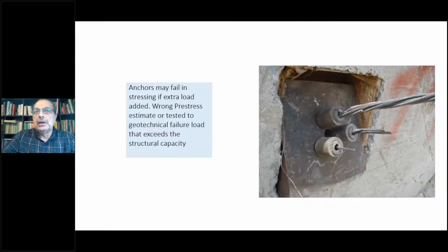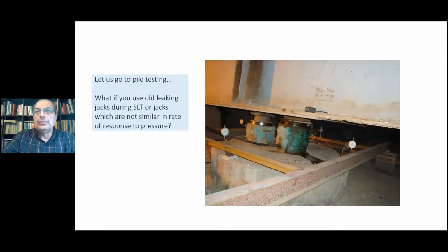So the geotechnical engineer is responsible also to check his anchor's structural capacity and not only geotechnical capacity. And he should follow standard methods of stressing these anchors and testing them before approving the anchor and leaving it peacefully. Also, the anchors should be retested after a while because there will be stress relaxation.